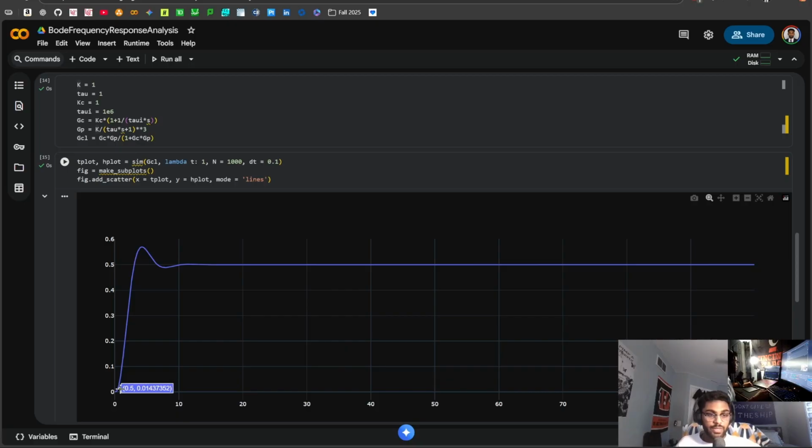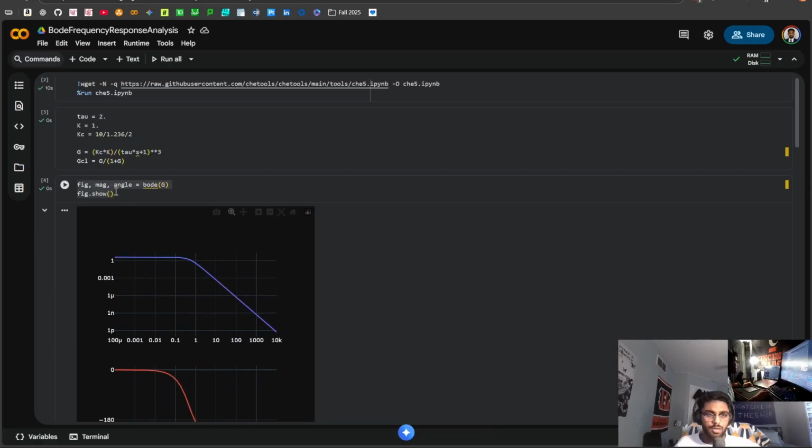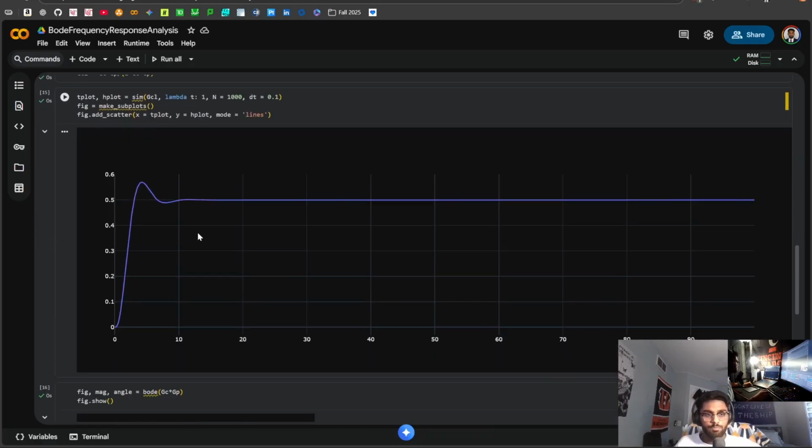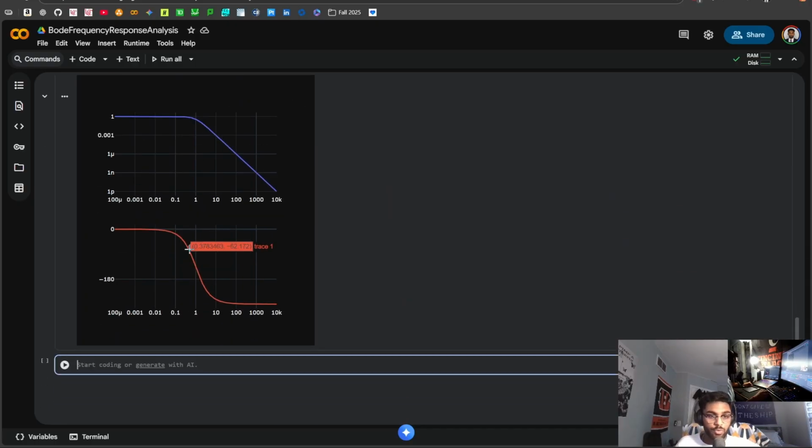we see that we get this frequency response graph that we have actually done the same thing right here. This is all just copy and pasted from above. And we see that if we look at our crossover frequency, like we had done last time, that crossover frequency looks like maybe like 1.8, let's say.